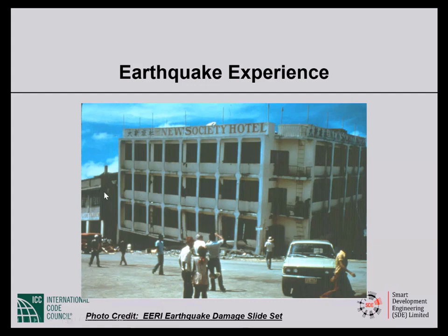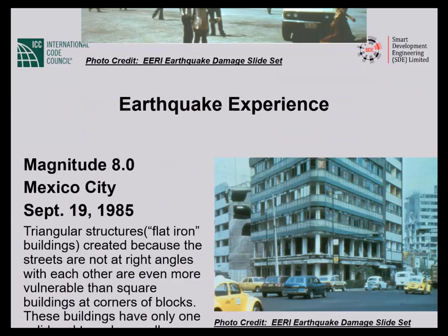So typically, you would have shear walls on the left face of this kind of a building and on the back face, but on the street facing faces, there would be no shear walls, for obvious reasons. And that means significant torsion. And because of the torsion, the ground story has failed. The building, at least in these parts, is one story shorter than it was before the earthquake. So torsional irregularity is a problem.